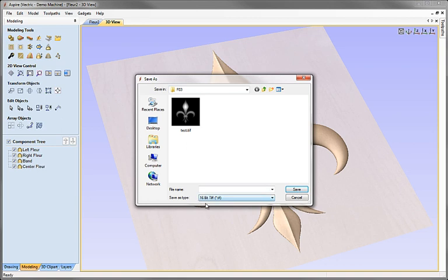That is obviously much more accurate and smooth if we choose to import that back into the software at a later stage. Whichever one we choose, we just give it a name, hit save, and then we've created, in effect, a 2D representation of the 3D file. Any transparent areas in the image, like we can see in the modeling plane here, will be exported as black, and then all the heights within the model will be exported, interpolated from white at the highest points down to black at any points which are at the bottom of the part.